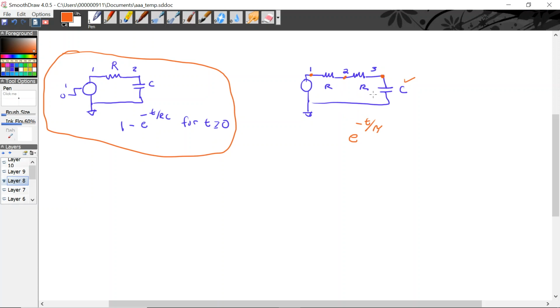One easy way of looking at tau is to see, well, here's the voltage source. It has an impedance of 0. And we have 2 resistances and a capacitance, so just going around the loop. By the way, this is a really quick way, but not necessarily a generalizable way, to do these problems. But we're going to get 2RC for our tau.